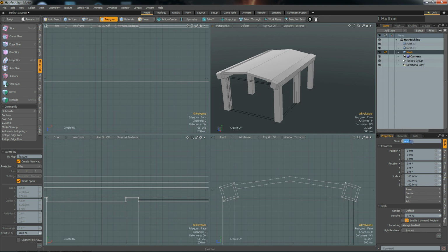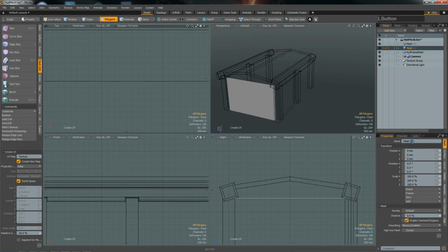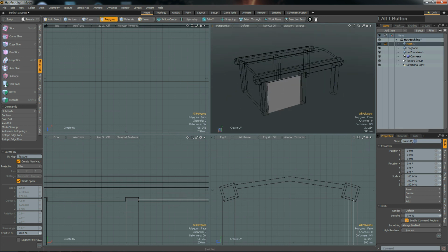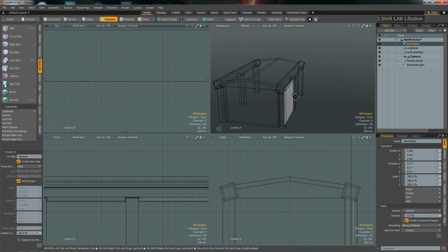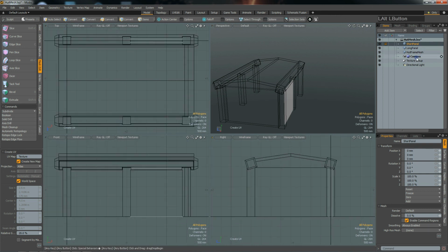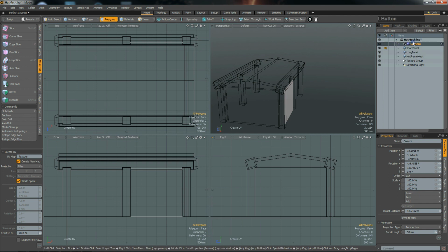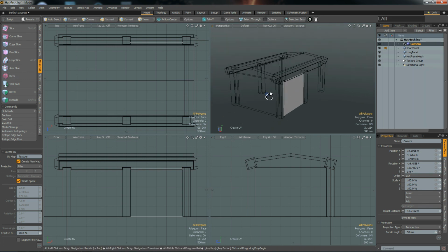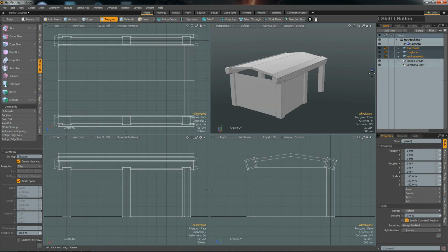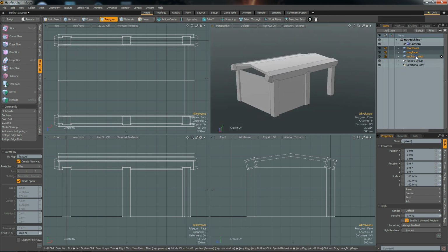And now we're gonna name our layers. This would be the HUD frame mesh, if I can spell that right. This would be the, let's just call it long panel as opposed to the short panel. Later, when we create the real HUD, we will use better names, and then also the roof will be an entirely separate piece, so we can have different roofs. Just wanna point out how it's done here on a high level, and for just a mock-up prop, it's good enough.